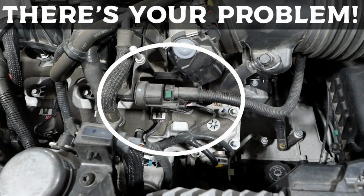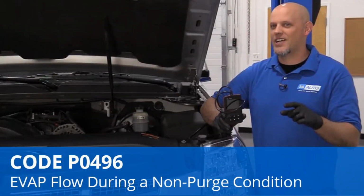What are the common symptoms of P0496? In some cases, an illuminated check engine light may be the only symptom accompanying a P0496 code. However, other problems such as vibration or other engine performance problems can also occur if fuel vapors are purged at the wrong time. Professional tip: a very common problem with a purge valve stuck in the open position is that it can be difficult to start the vehicle after refueling. This can happen on almost any vehicle, but is common on Fords and some Kia models.